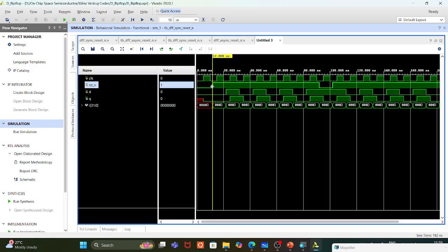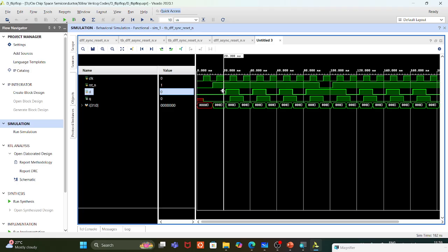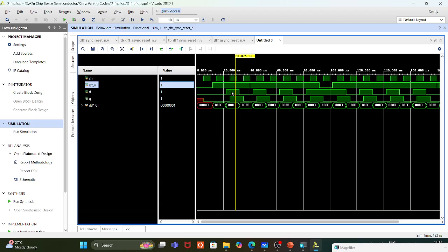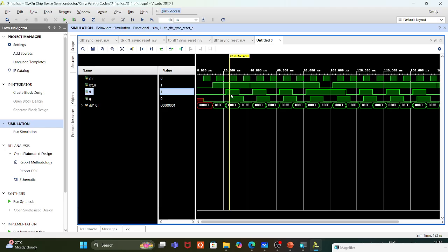Reset mode to functional mode means the output is not going into the functional mode immediately. It is only during the passage of clock that the output follows the input. There will be delays there, like setup time and hold time violations, that will come in static timing analysis. And this is nothing but reset, functional mode. Reset removal. So what I told, like asynchronous reset, the reset applied is nothing but synchronous with the clock.